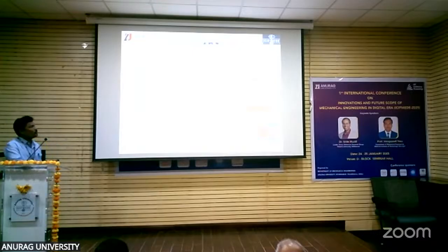The first one is the aluminum alloy block, and the other is the die steel. Copper electrodes are used as the cutting tool. These are the different properties of the aluminum alloy and the die steel. Then this is the methodology, the structure for the Taguchi design. The parameters are discharge current, voltage, pulse on time, and pulse off time, with 4 levels: level 1, level 2, level 3, taking different values. The total array is the L16 array, so 16 trials to conduct the experiment. This is the experimental setup for this operation.